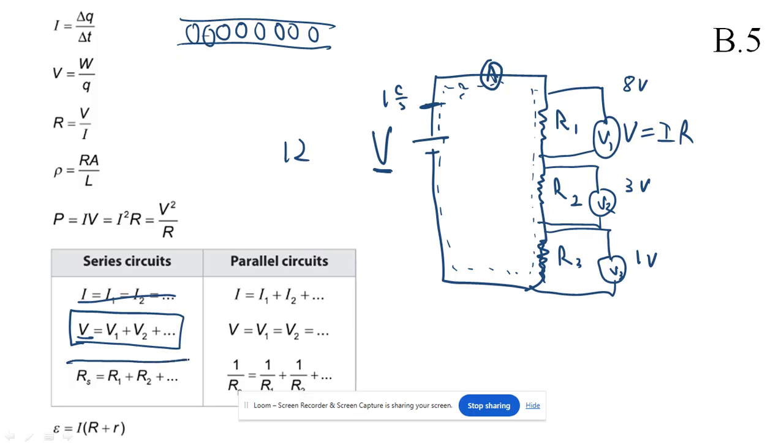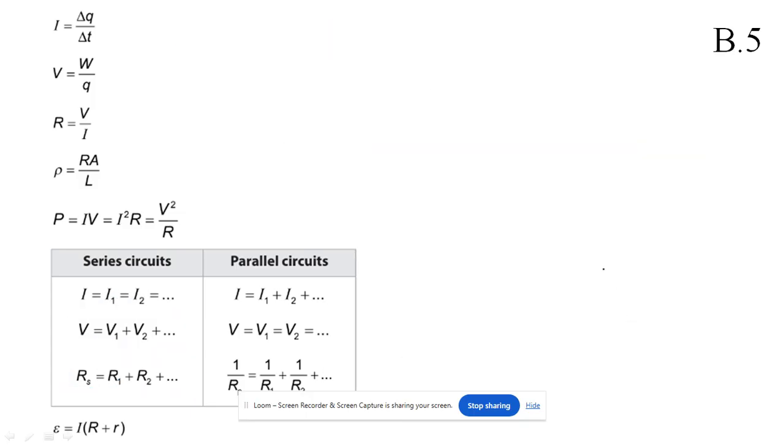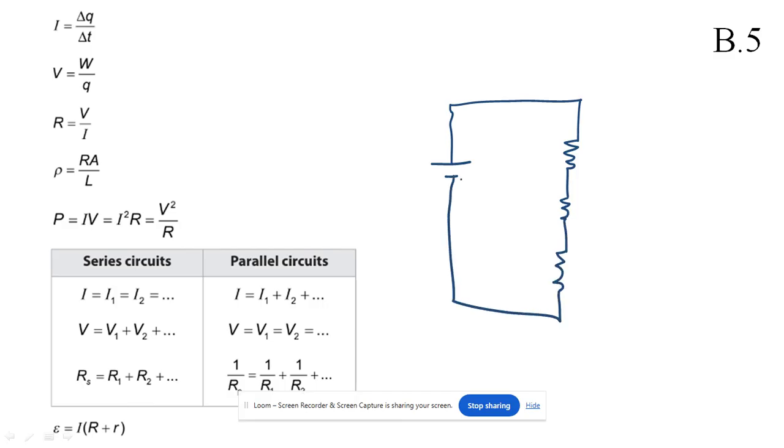And then here, the resistance in series is literally just add up all these resistors, right? Okay. So if I've got these 3 resistors, let's imagine that this is 6 ohms, this one is 4 ohms, this one is 2 ohms. Let's imagine this is 24 volts. We have to have the number come out even, right? Our resistance is going to be 6 plus 4 plus 2 is 12, right?